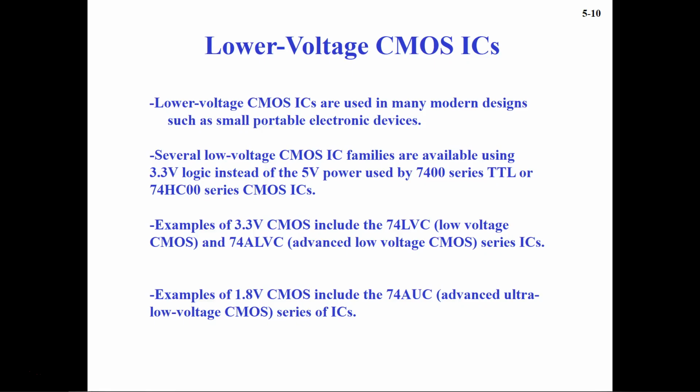And the second reason is that as the industry has moved towards even smaller components, the CMOS transistor's gate, source, and drain are getting even thinner, and thus incapable of insulating voltage potentials as high as 5 volts. That's why we have such low voltage CMOS these days in the market.